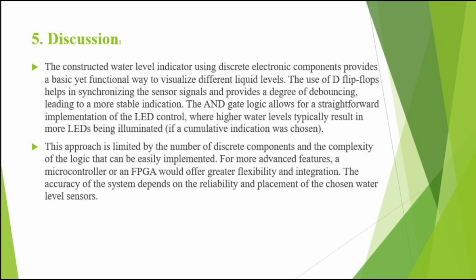The AND gate logic allows for straightforward implementation of the LED control, where higher water levels typically result in more LEDs being illuminated if a cumulative indication was chosen. This approach is limited by the number of discrete components and the complexity of the logic that can be easily implemented. For more advanced features, a microcontroller or an FPGA will offer greater flexibility and integration.